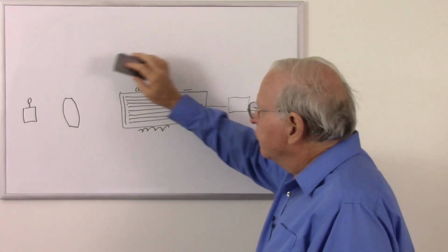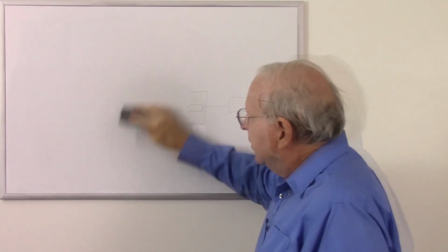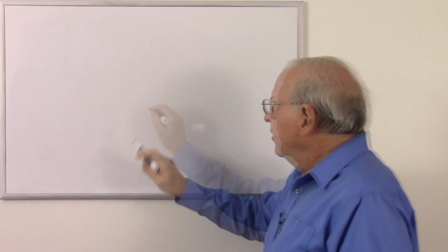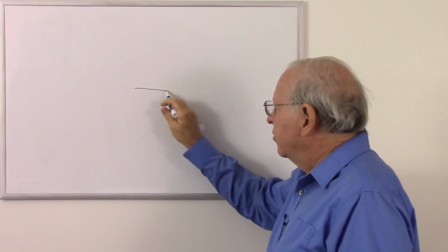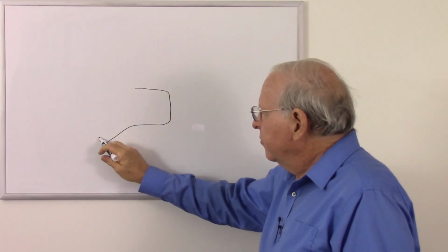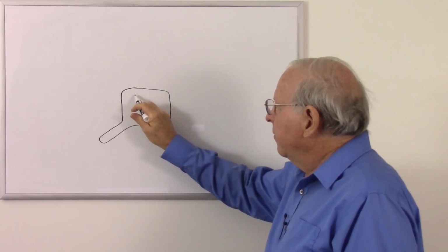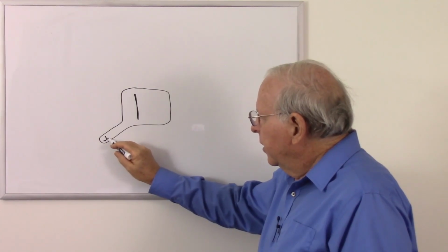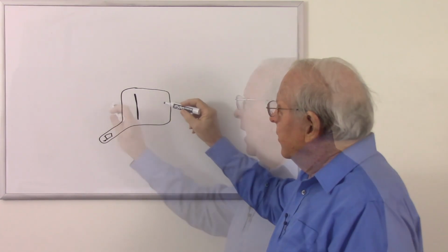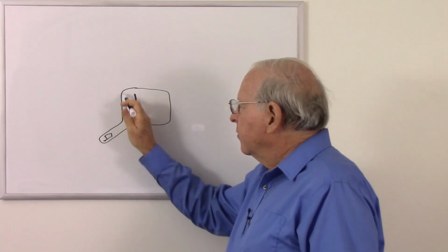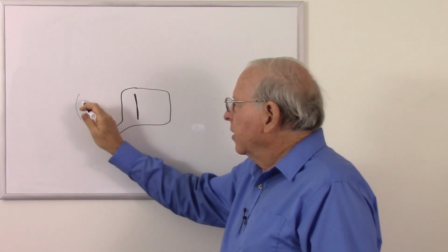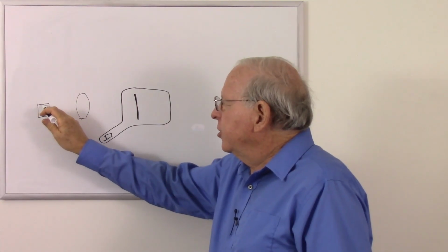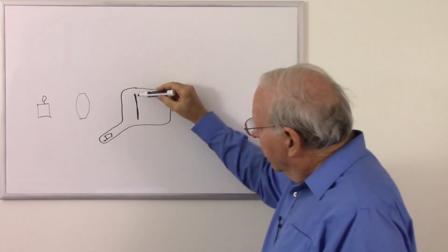So Vladimir Zworykin is credited with developing the iconoscope, which worked on a different principle. They had different shapes, but the original that's usually shown in diagrams is shaped sort of like this. We had an imaging plane here, and our electron gun was down here. And we had a window here basically, so this part of the tube was flat. Here is our lens out here, forming our image on this part of the plane.